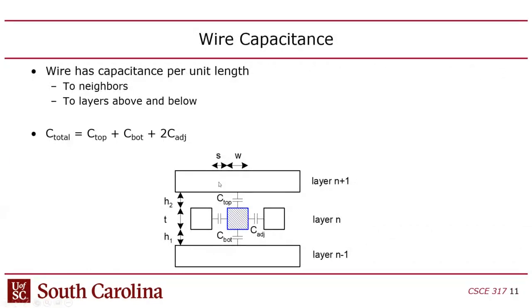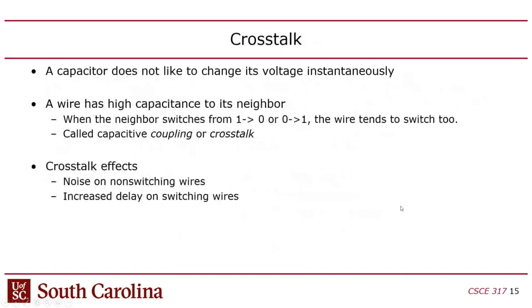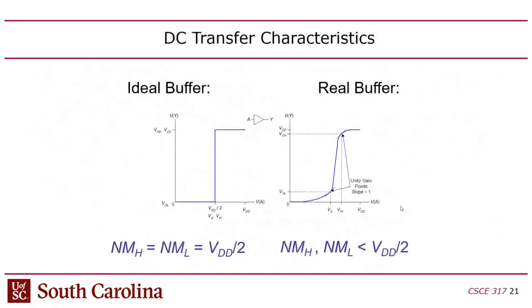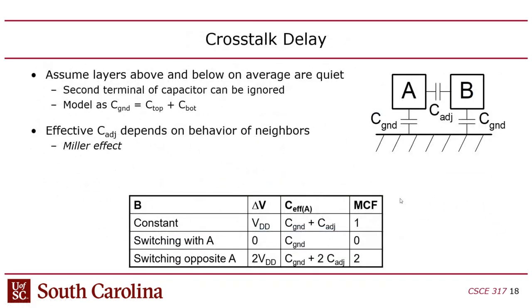I mentioned that we're not considering this top plane. We have this ground capacitance, and then there are these neighboring capacitances. So technically, we actually are considering these neighboring wires here, with this Miller effect. So we're adding additional capacitance to these neighboring wires.